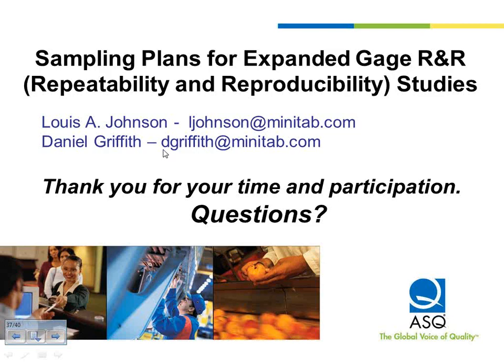We want to make sure this measurement system can be used over a range of different parts. So we're going to add a little bit of practical application to our theory about what's happening mathematically, and that's kind of where we came up with 4. But I would agree wholeheartedly that they've done a lot of good work on how to reduce your sample size for a lot of scenarios. They're going to study fixed additional factors and only 2 levels of a factor and so on. So yeah, definitely a lot of good work done by those 3.